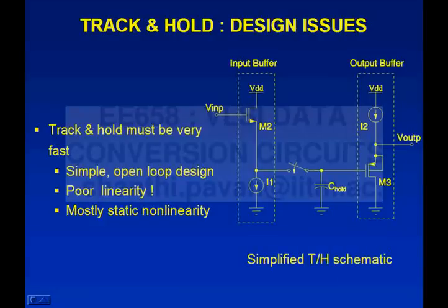And this is only one half of it. Please note that we are going to be using fully differential inputs, which basically means that this is the half circuit for the track and hold. This just processes the positive part. There is a copy-paste replica which processes the negative input. So the input is V in P, V in M, and the difference is what your input signal is. The output of interest, the output of the track and hold, is not this voltage or V out M. It is the difference between those two voltages. So the question is, why is it?